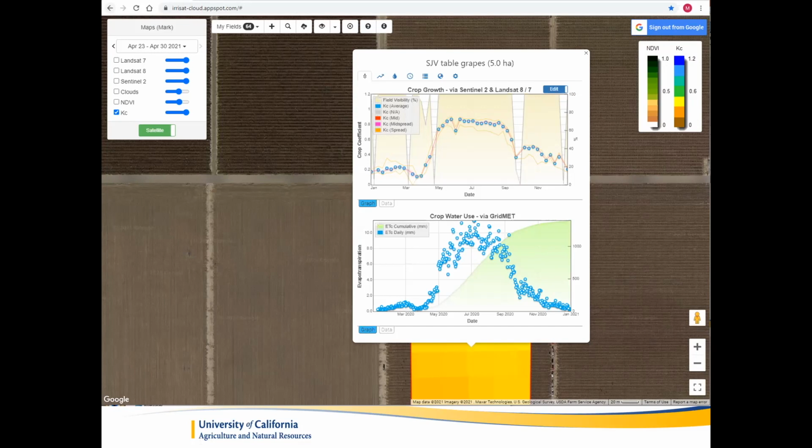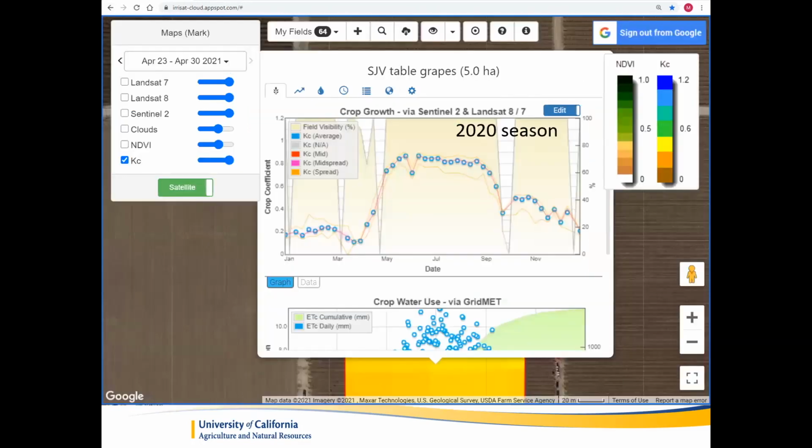And for that reason, this probably is not accurate for the types of crops that we're growing in California for the most part. So think wine grapes or almonds, any crop where we are using deficit irrigation, this calculation is not going to be accurate. So I would not use this other than as more of a curiosity, until maybe in the future, if this program adds a deficit factor, then we could do some additional calculations with this. But for the time being, let's just look at the crop coefficient value, and you can see the pattern here.